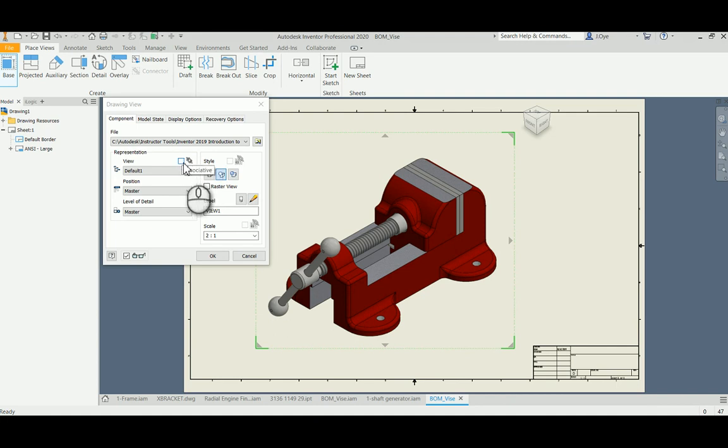So if I leave it checked, I'm saying I want to be able to have my drawing view update to any changes that happen in the assembly model, or do I not want those updates to happen? So the update to 2020.1 is just for Inventor to remember if you had it checked or unchecked. So the next session I open up Inventor, this associative link would be checked.